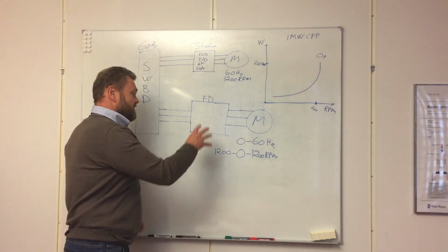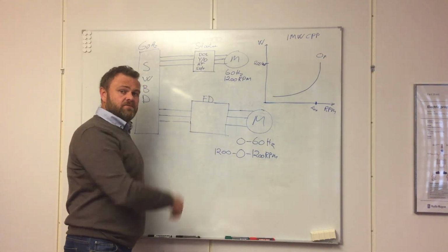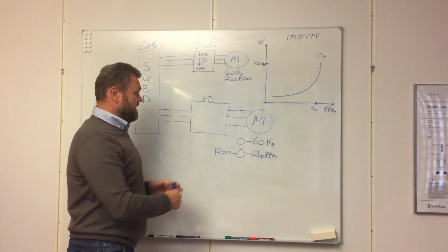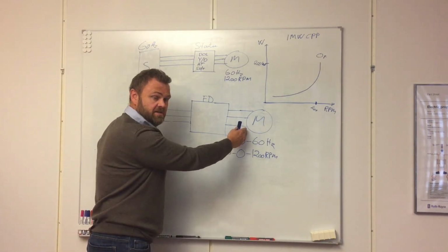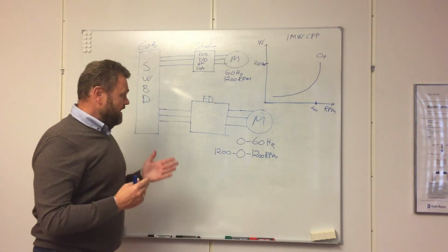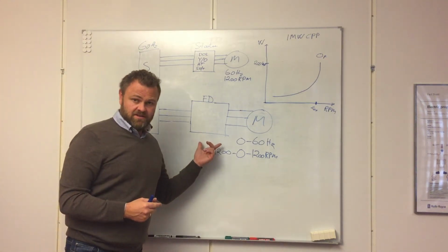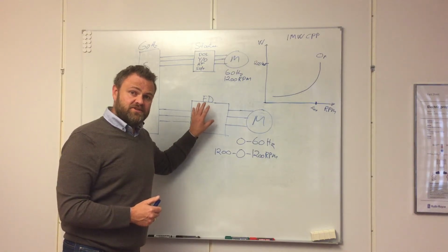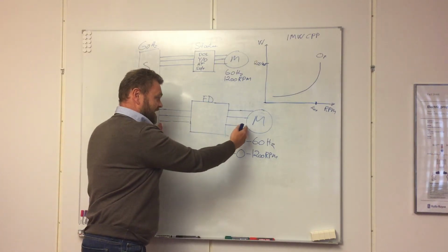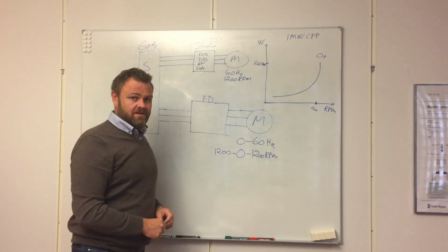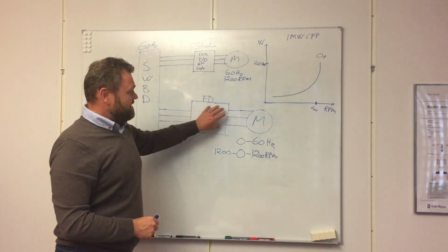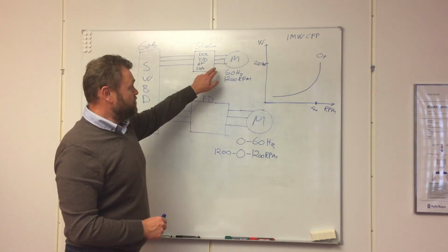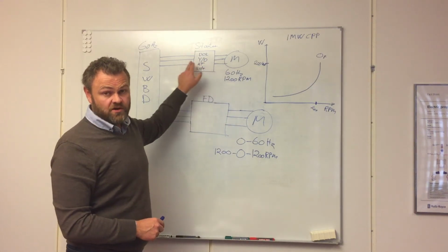So the frequency drive itself does not reduce any loss in the electric part. It is in fact the opposite. The frequency drive itself will add some losses in the electric system, because it is electrical losses through the frequency drive that you do not have with a starter.